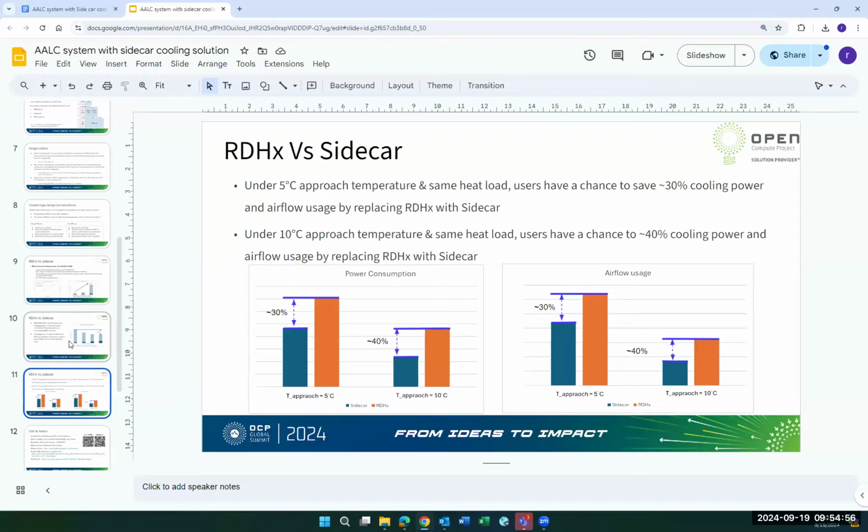And the last one, I think this is a little straightforward. The majority of the power consumption of the CDU comes directly from the fan. So I think this kind of makes sense. Power is directly correlated to the airflow, because the majority is coming from that, and from pumps it's minor power, and the approach temperature is directly proportional to the airflow that you use to get that.